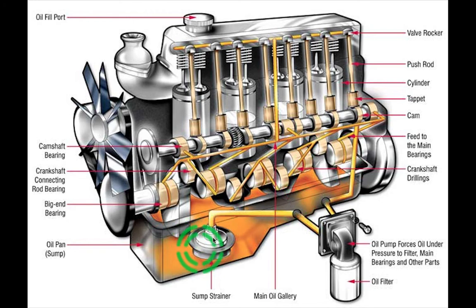So this is how it works. Here you have that strainer thing, which is your pickup. Yeah, that's what they call it, pickup. From here, the oil goes through the filter, and then your oil pump, which is driven by the crank. Some pumps are external and electrically driven.